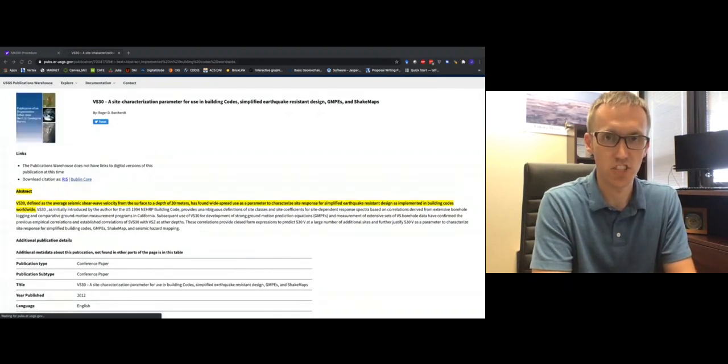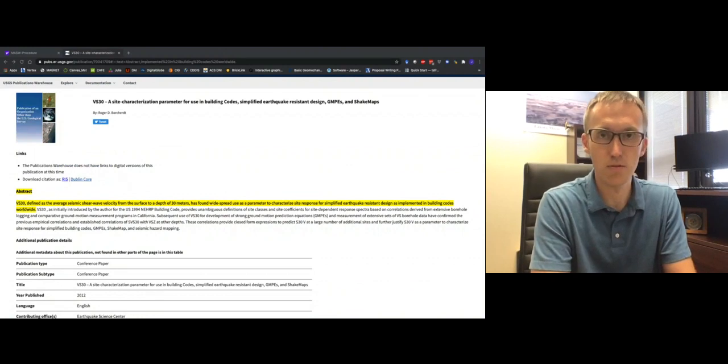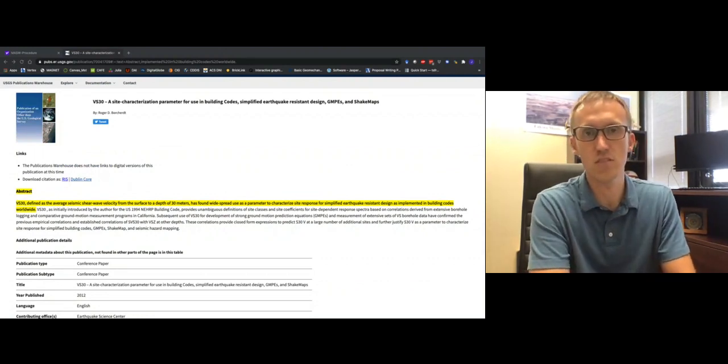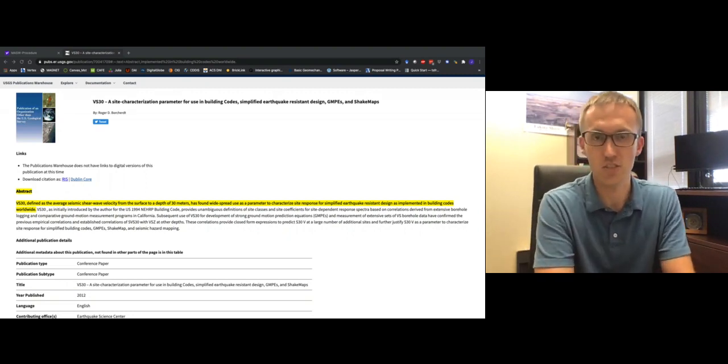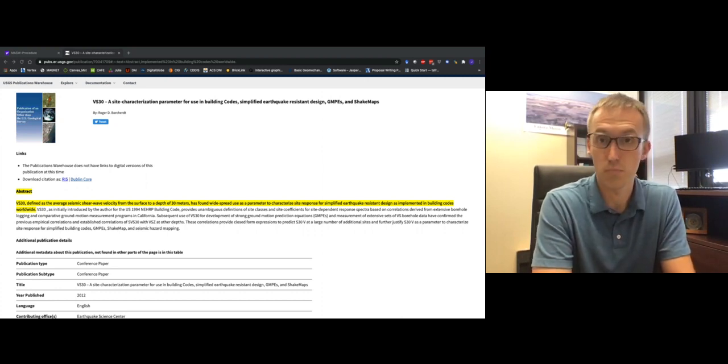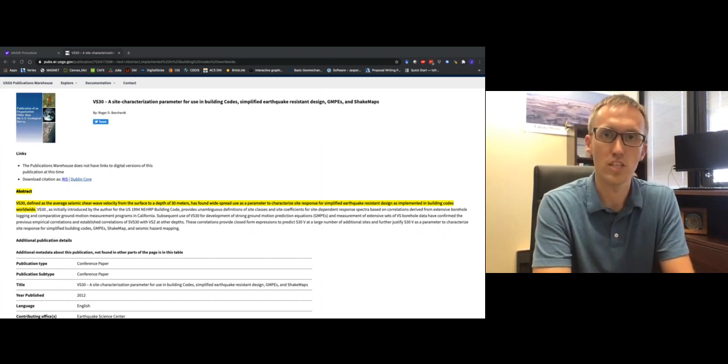Hi everyone, this is Dr. J, and in this video we're going to talk briefly about MASW, or the multi-channel analysis of shear waves method for seismic site characterization. Now the motivation for this is that in terms of looking at buildings or roads, bridges, landfills, you name it, one of the most important geotechnical properties for site characterization is what's called VS30.